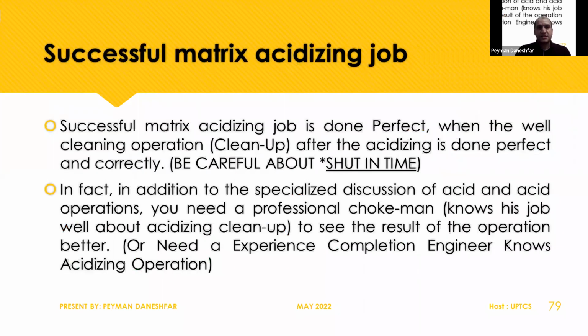And successful matrix acidizing jobs happen when we know about our shut-in time. Shut-in time means that after acidizing jobs, the well in a carbonate formation absolutely should be opened, or cleaned up, immediately after the acid job finishes. But in a sandstone formation, you can wait for some minutes. But the shut-in time in a carbonate formation is 0. And we should know about this one.